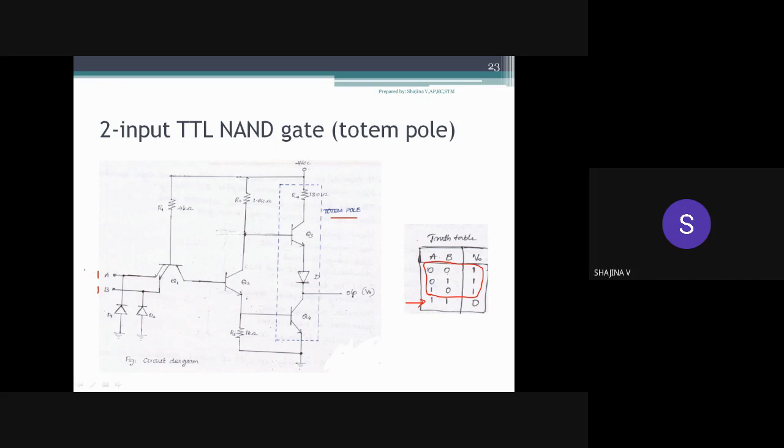Okay, in terms of analog, I am applying 5 volt to these two terminals A and B, or we are applying logic high values. You needn't remember the analog values, we are applying logic high value. So since here it is 0 and here it is almost plus 5 volt, this diode is reverse biased. So in this case, D1 and D2 have no role. When positive comes, it will be reverse biased, not conducting, that will act as open circuit. Okay, so it has no role.